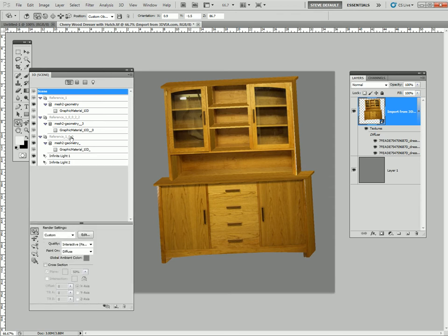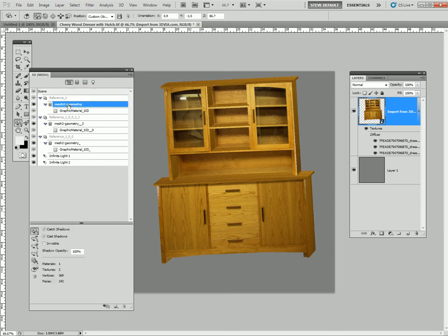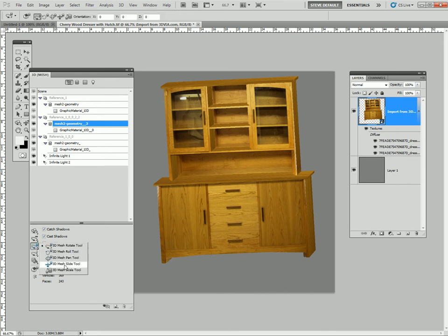Okay, so we can see several meshes. Now if I select the mesh, I can select any mesh that I want to manipulate. And in this case, I'm interested in actually splitting these apart a little bit so that I have some depth in between each of the objects. So right down over in here on the lower left hand side of your 3D mesh layer, I'm going to click and hold, and I'm going to select the Z depth tool.